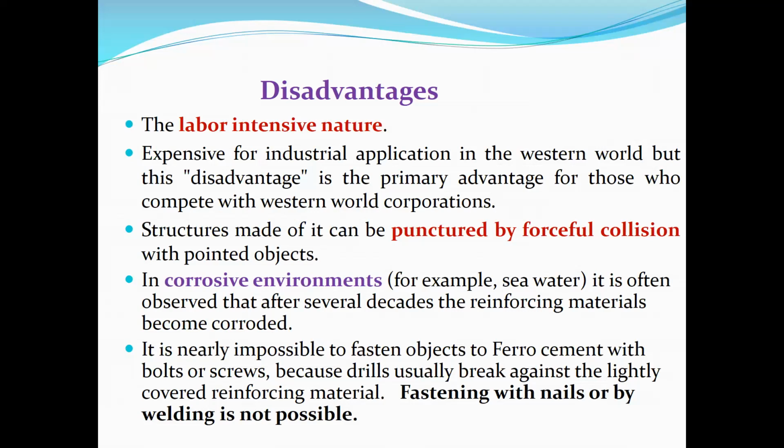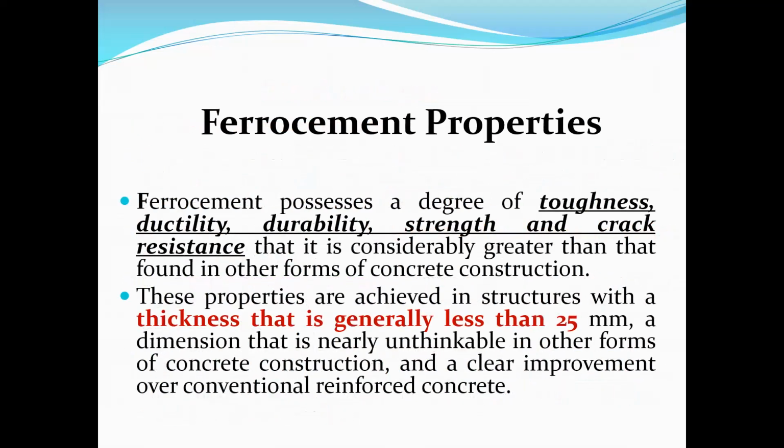It is generally impossible to fasten objects to ferrocement with bolts or screws because drills usually break against the wire mesh. On a normal concrete wall, you can drill and hang something, a switchboard or a clock, you can do anything. But the ferrocement structure is only about 2 inches thick, so you cannot drill and fix anything there. This is mentioned as a disadvantage.